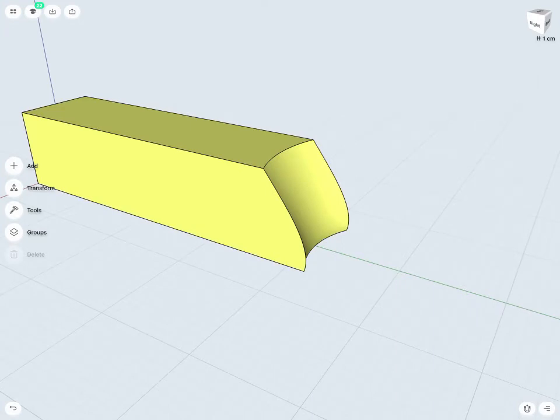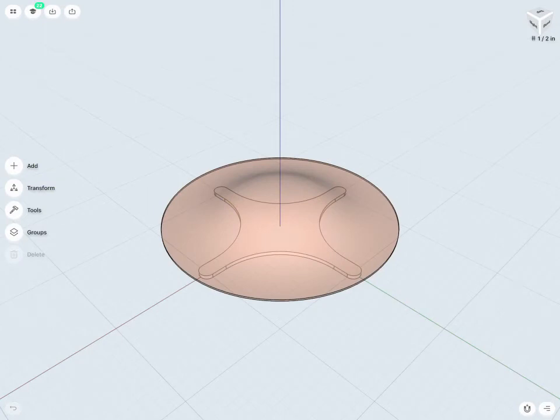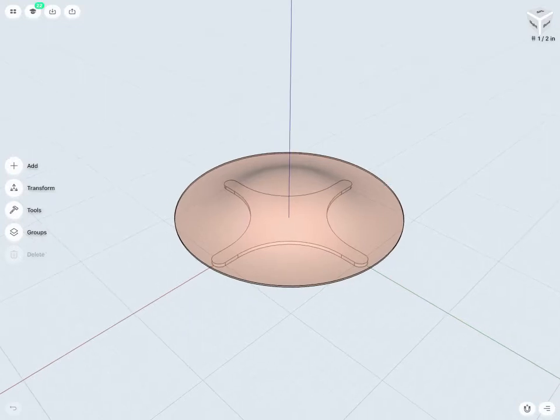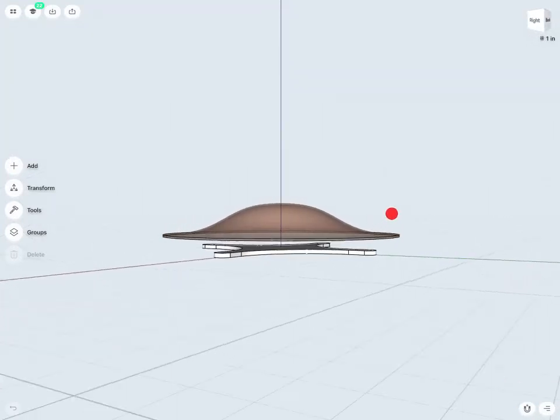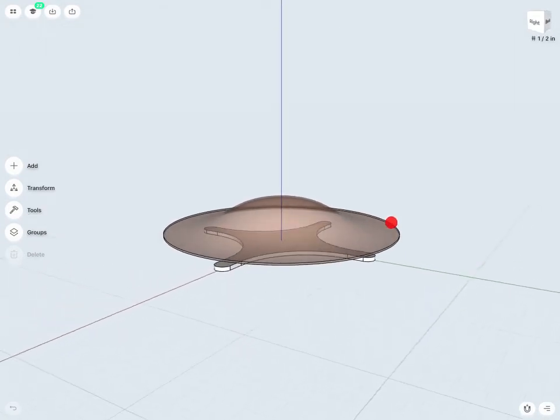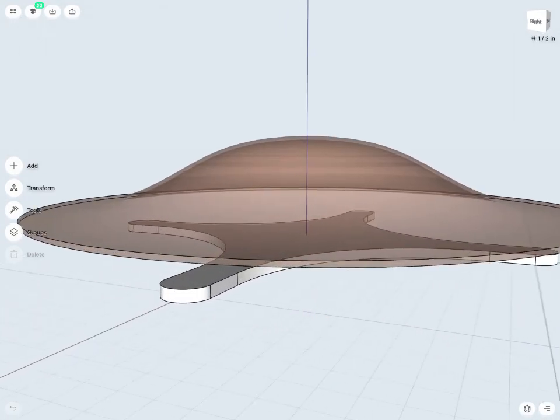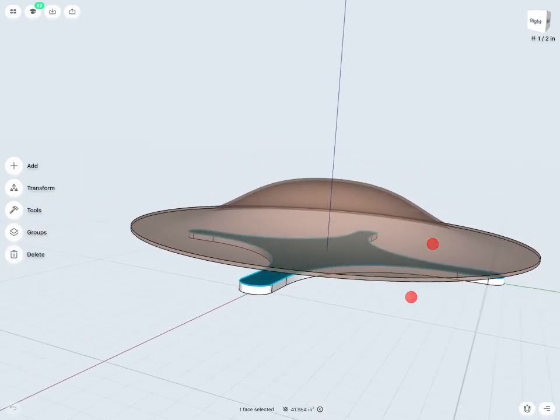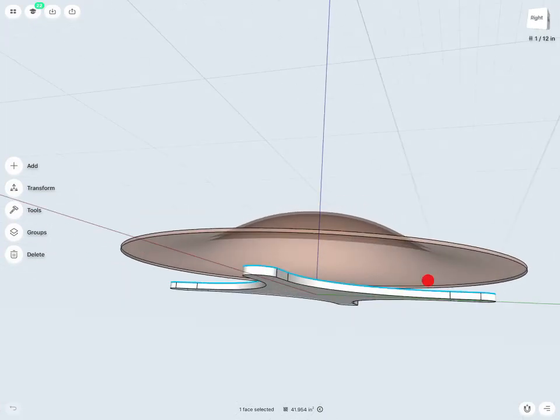So now that we understand the basics of the Replace Face tool, let's take a look at using this in maybe a slightly more complex design. So, in designing the top half of, let's say, a drone enclosure, it's a pretty complex, natural, free-flowing shape. But what I could do here is design this quite easily just by using two unique bodies here. And what I'm going to do is now tell this face here to use the Replace Face command with, say, the under face here.